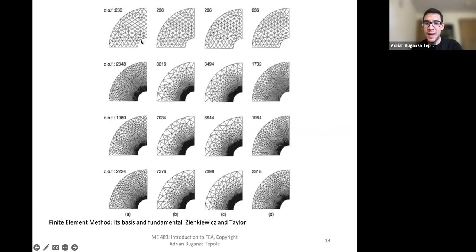There's adaptive meshing in Abaqus. We didn't do it, we kind of did it manually, but there are some features in Abaqus that will allow you to do adaptive meshing, which is that as it solves the problem, it will try to calculate where in the mesh you should have more stress gradients, and therefore you should refine your mesh. So it will automatically do that for you. We didn't do it, but there's automatic remeshing in Abaqus, basically monitoring the stress gradients and increasing the mesh size in those regions where you have greater stress gradients.